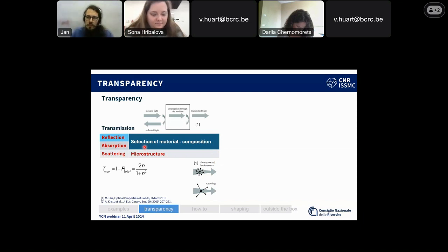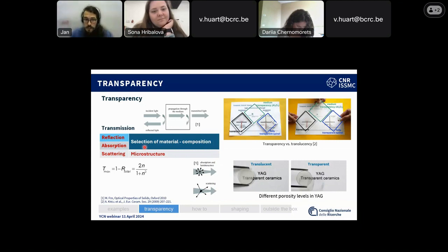And so, okay, we found out that if we use air presintering and hot isostatic pressing, we can actually, by co-pressing the parts first into one single compact, get a composite part that is transparent and works, and in this case allows you to see both X-rays and neutrons.